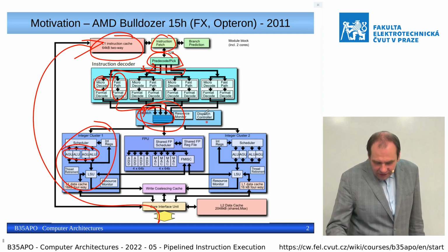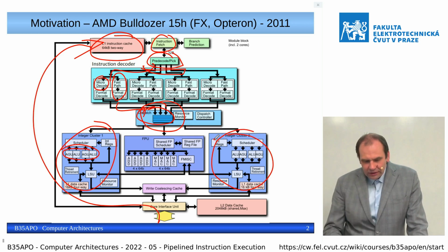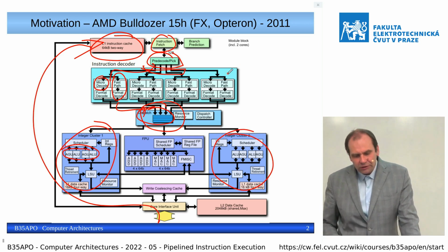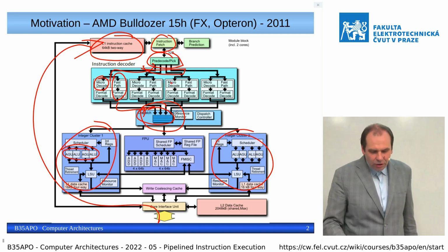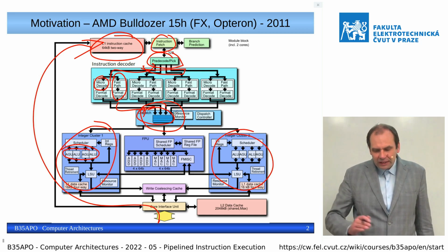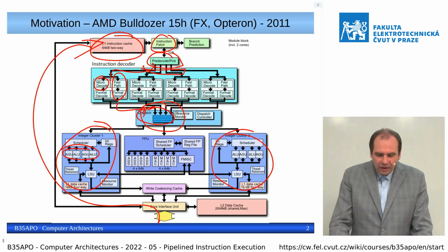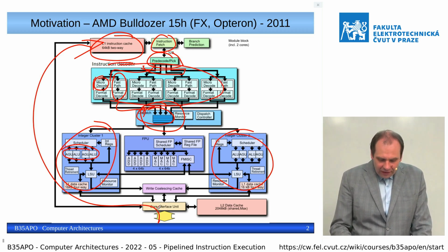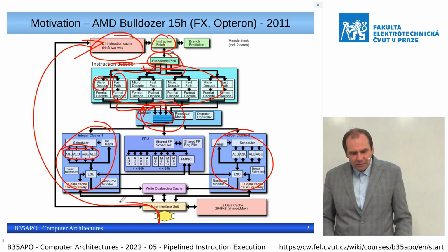And we have those integer channels doubled because this CPU is able to decode instructions from 2 instruction streams. So in fact a single core on the chip behaves as 2 processors from the software point of view. So basically the units can be utilized even during the time when the execution blocks on access to the main memory and so on.